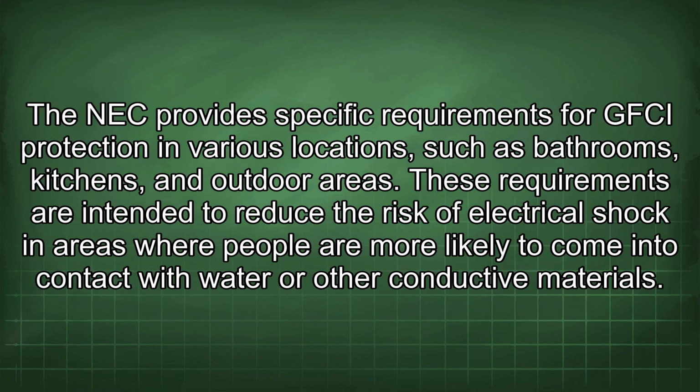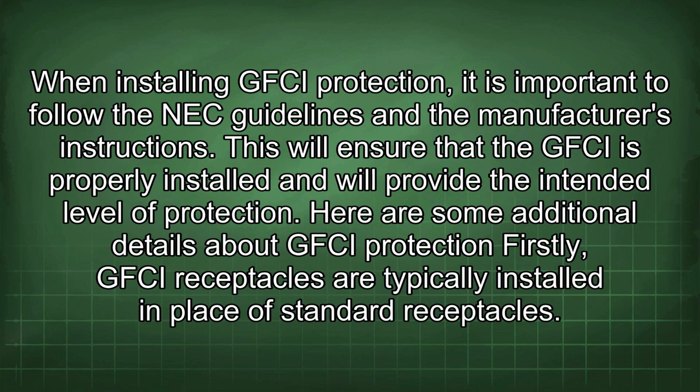The NEC provides specific requirements for GFCI protection in various locations, such as bathrooms, kitchens, and outdoor areas. These requirements are intended to reduce the risk of electrical shock in areas where people are more likely to come into contact with water or other conductive materials. When installing GFCI protection, it is important to follow the NEC guidelines and the manufacturer's instructions. This will ensure that the GFCI is properly installed and will provide the intended level of protection.